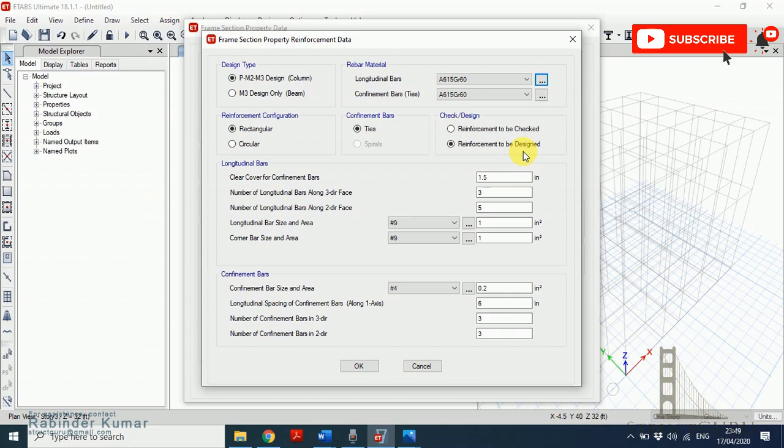Reinforcement to be checked means if you click it, you have to provide all this information. You have to provide the bar size, bar number, number in x direction, number in y direction, and what spacing you are providing. In this way, ETABS will check according to your given data.